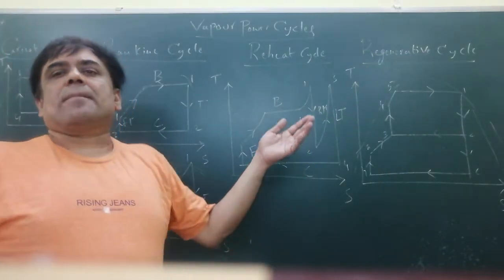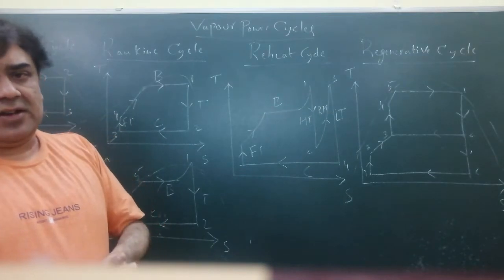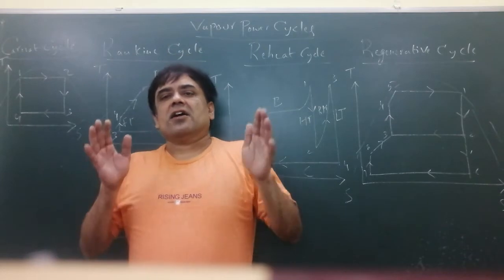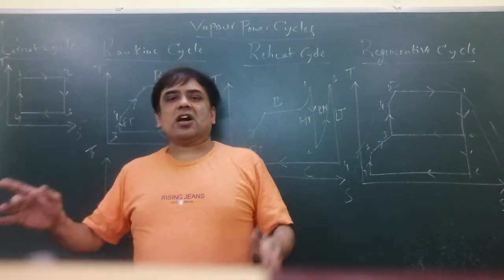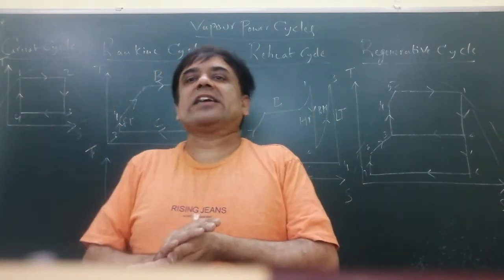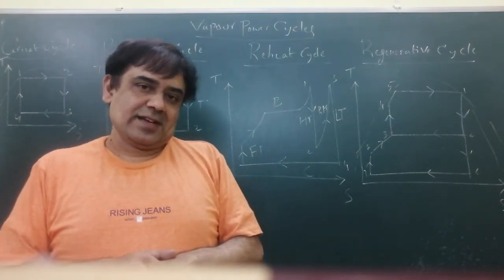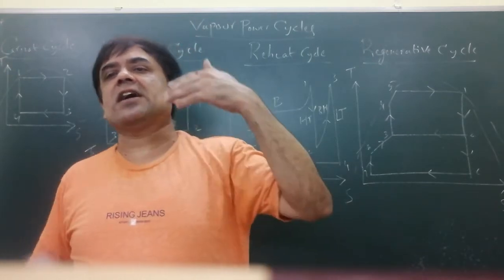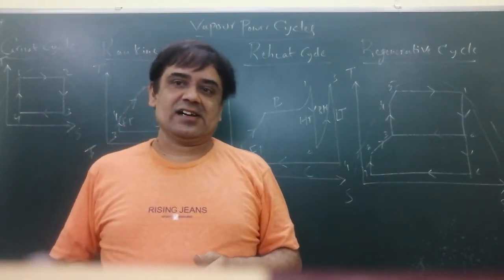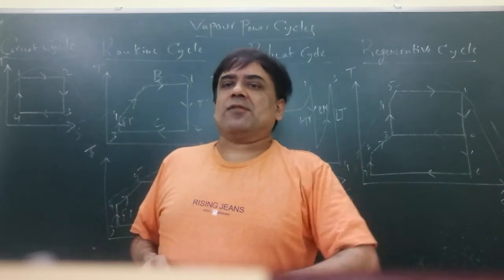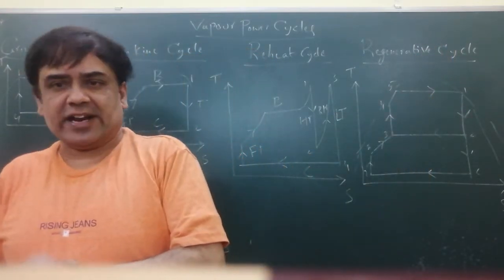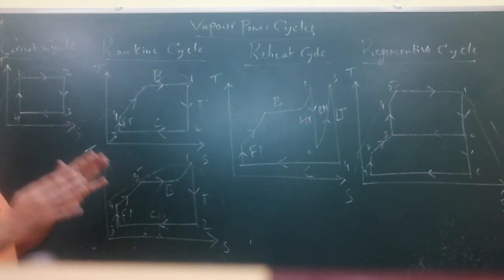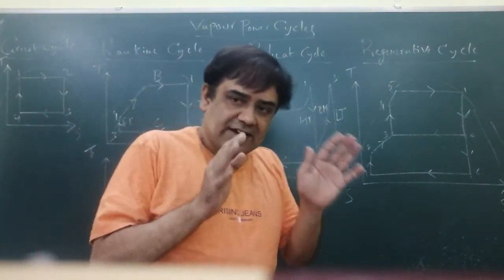You all know practically it is not viable. There are some limitations. In the case of the Carnot vapor power cycle, it is not possible to compress the wet vapor isentropically. Next, it is not possible to judge or adjudicate the quality of condensate. So, like this, we have one or two other limitations wherein practically it is not viable. That is why this is just taken as a reference.